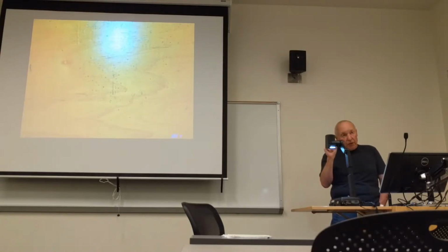When we get to timing closure, we're going to see that to get timing closure, you have to resynthesize a number of times with different synthesizer options, with recoding that you've done, so that Tcl file would have to be executed many times. So you would think, well, gee, this may be a long file, but I only have to type those in once. And you may not be certain that you've got all the commands you should have in there to properly do the synthesis. Well, you have a way out.